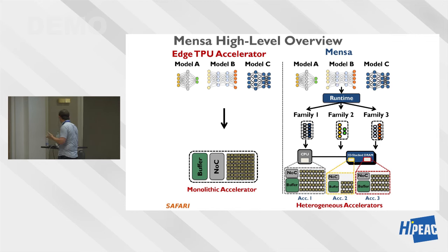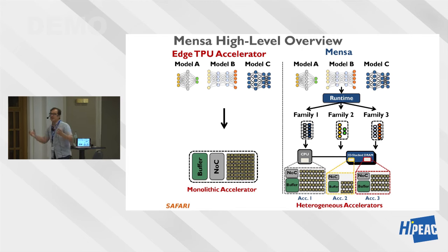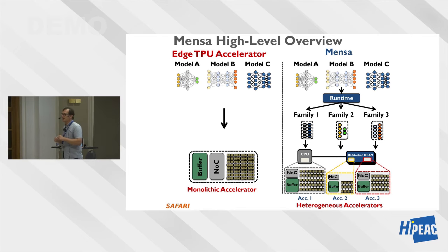It's essentially similar to this one, but it's much smaller because it doesn't need to deal with the memory-bound layers. The other 2 accelerators are under 3D stacked DRAM in the logic layer, and one of them is smaller, the other one's bigger, to deal with different types of, let's say, data-centric or data-intensive layers. And the data flows are also customized.